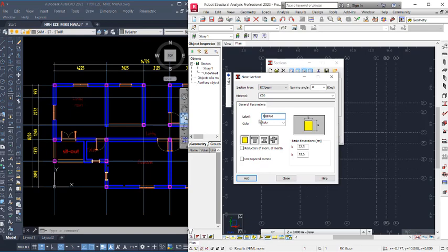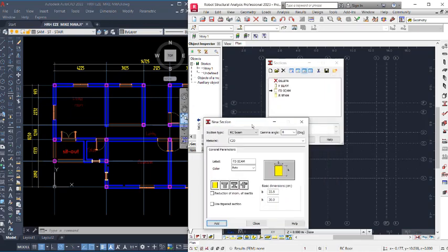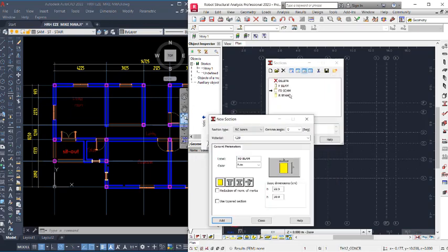So we also have FD beams. So this is foundation beam. Okay, so we still maintain this, it is going to be 300 millimeters, just like this. Click on add. All right, so once you're adding, you see it is showing in these provisions.